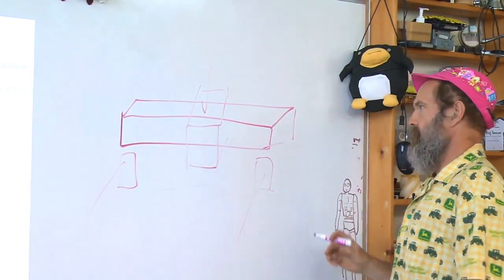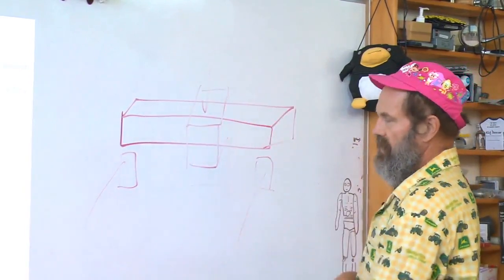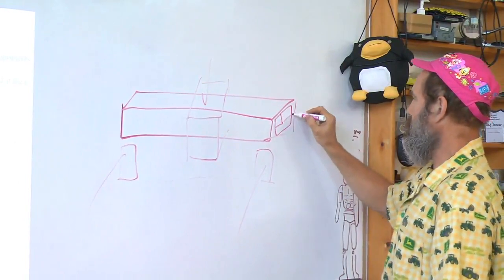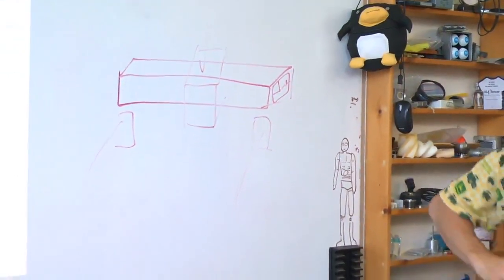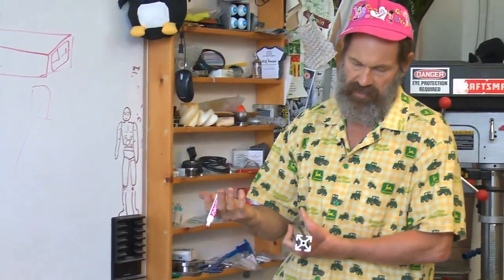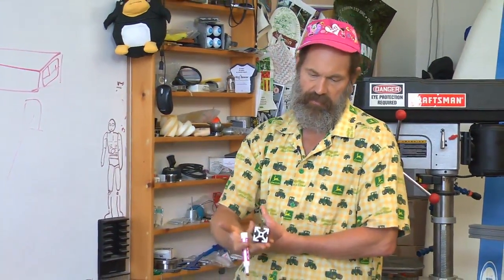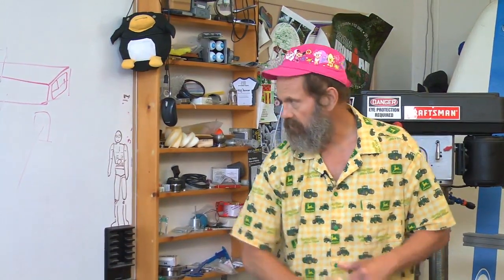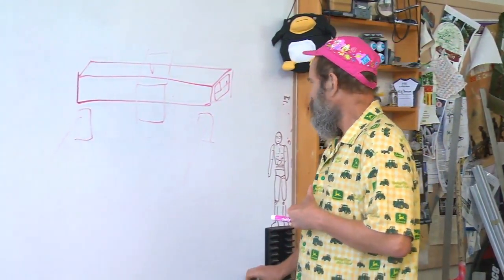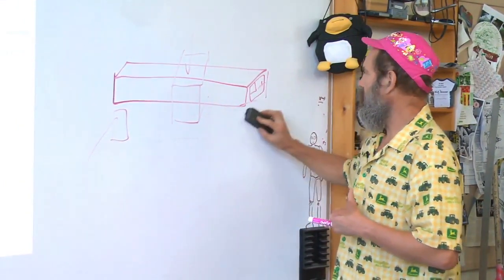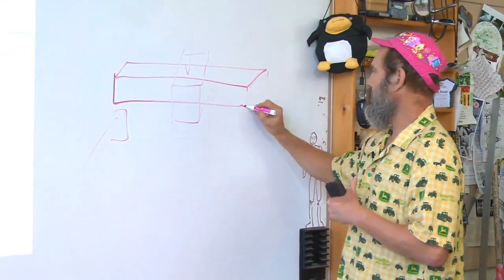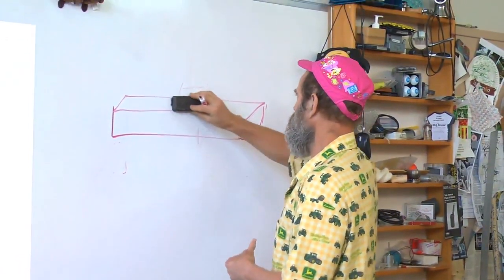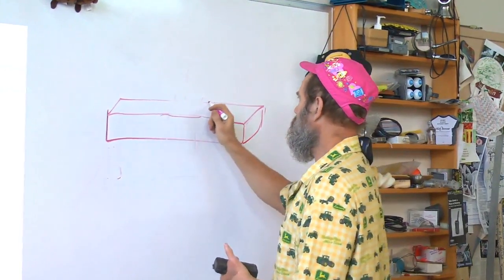And I'm looking at this beam and I want to know the deflection of the beam and the strength of the beam, and maybe I'm going to do that because this is some weird shape like we just drew earlier, this guy with the plates on it. And I did my first order analysis assuming that it's just the top and bottom plates that govern the stiffness. But I want to check it, particularly for things like torsional loading. Well, okay, I'm just going to take this beam and I'm going to simply support it, load it, see what the stiffness is.